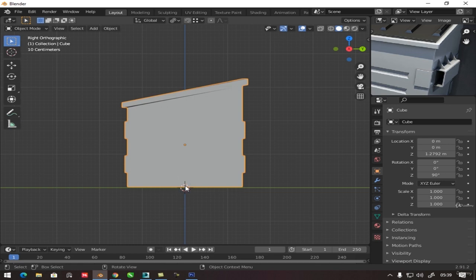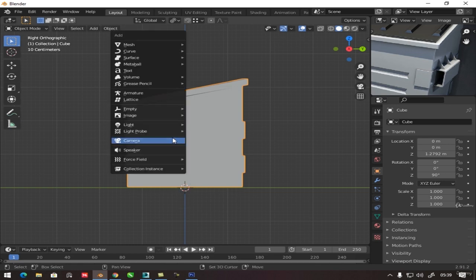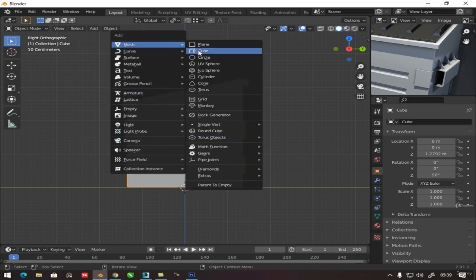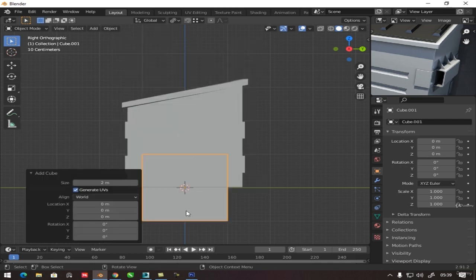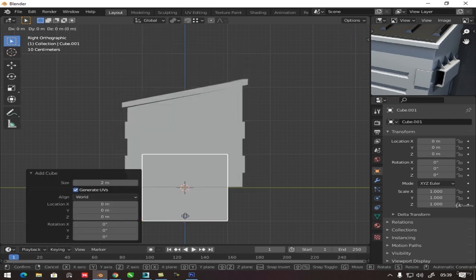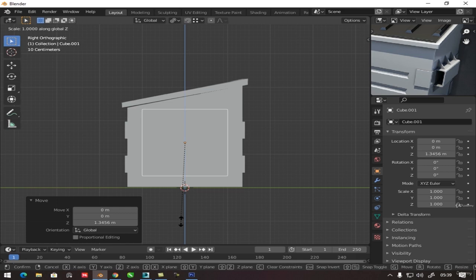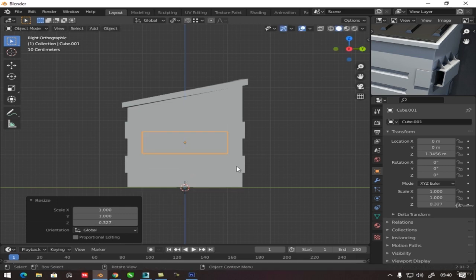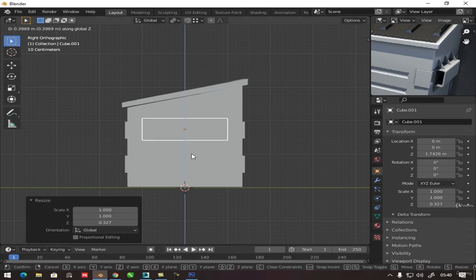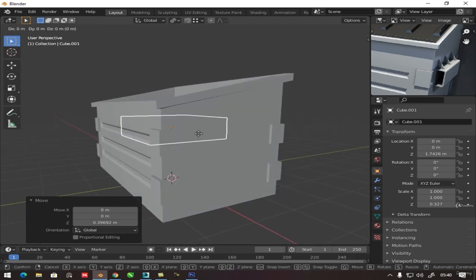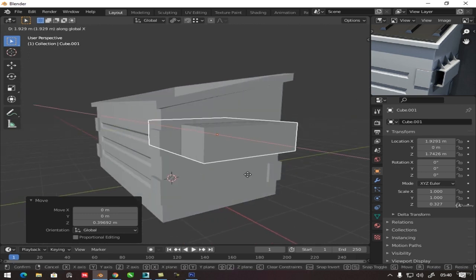It's very simple. We go to the lateral view and we will press, the 3D cursor is here, so I will just Shift A, Mesh, Cube, and then this cube I'll press GZ, bring it to here, SZ, I decrease in this moment, and you can see that it's basically on the length of this here. It goes almost nothing out, on the same size as well.